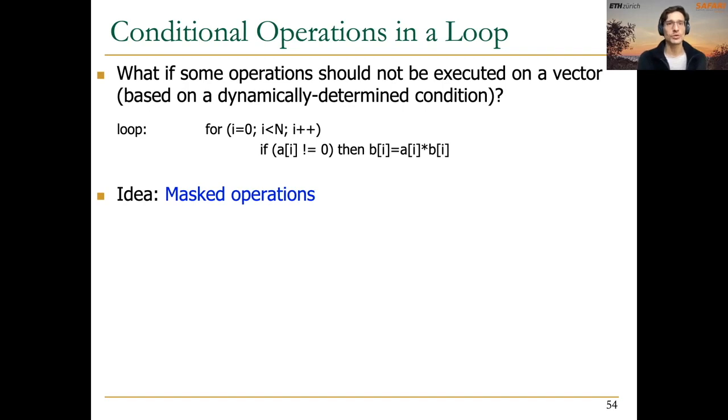What would you do? I guess that would be the first approach, right? Let's store one element per bank. Actually, I would say in all programs, even though they have very regular memory accesses, you will have streaming access patterns, which means that you access consecutive elements in memory, right? And from that point of view, I think it's reasonable to store consecutive elements in consecutive banks, because it will be very frequent in real world programs to have a stride equal to 1.